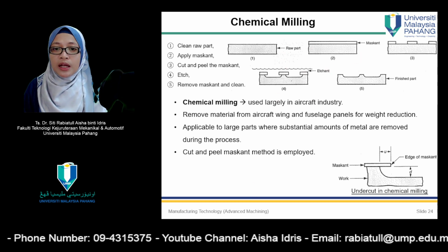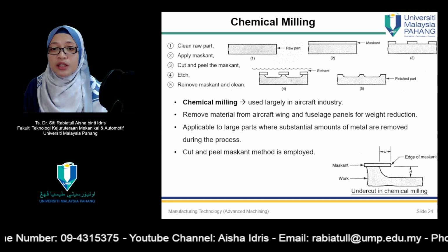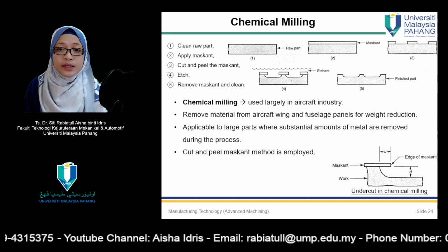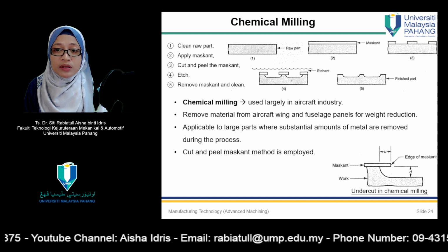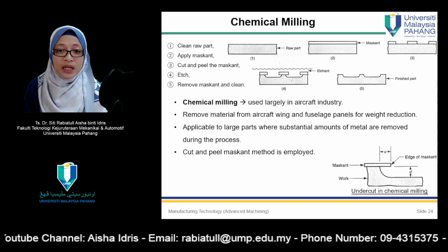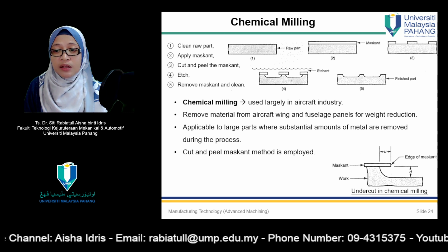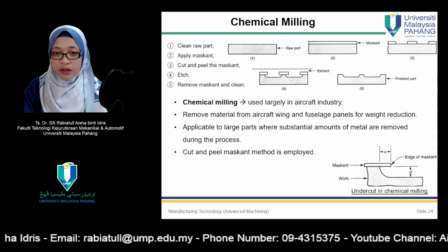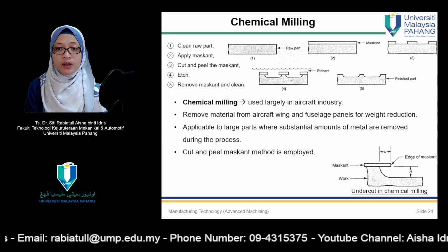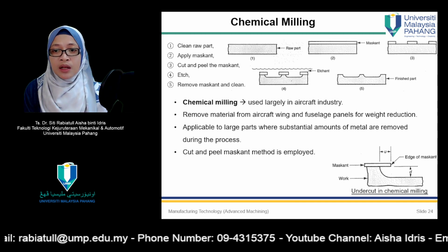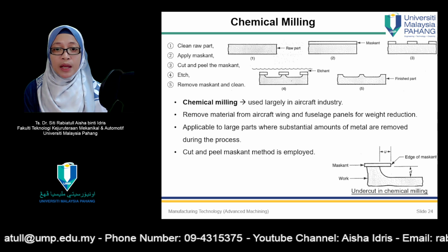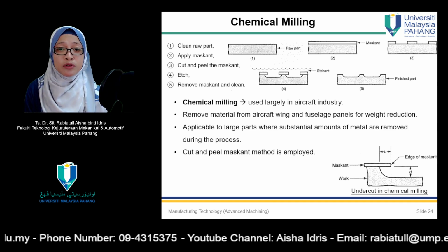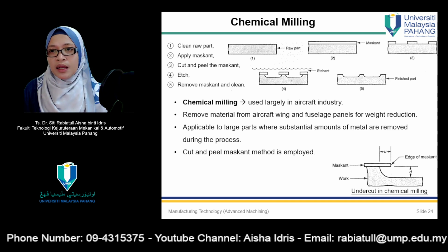All chemical milling produces a surface finish that varies with different work material. As depth increases, finish becomes worse, approaching the upper side of the ranges given for certain ranges of depth. And metallurgical damage from chemical milling is very small, perhaps around 0.005 mm to the work surface.